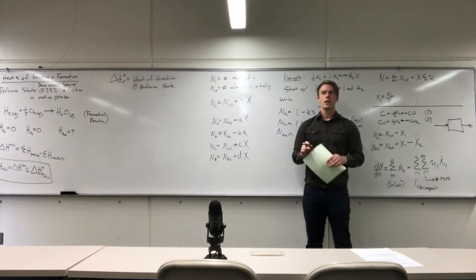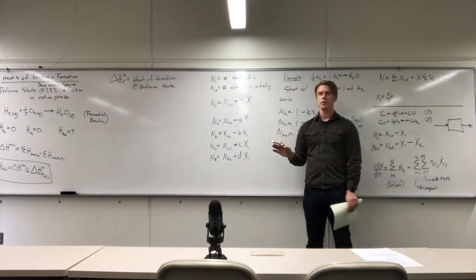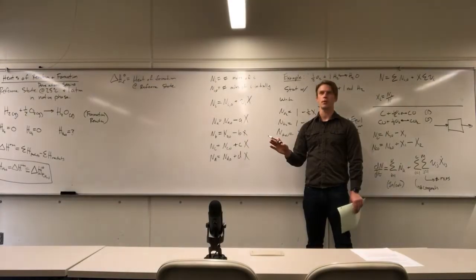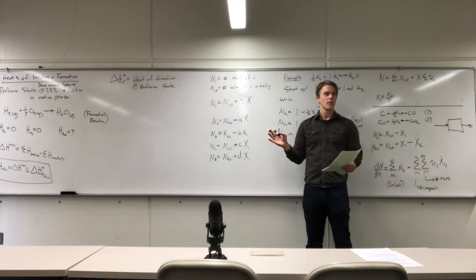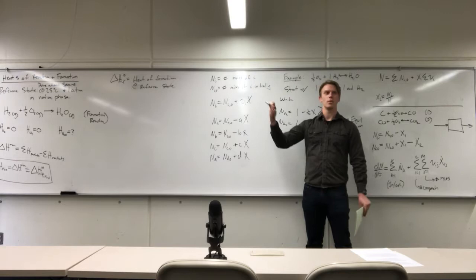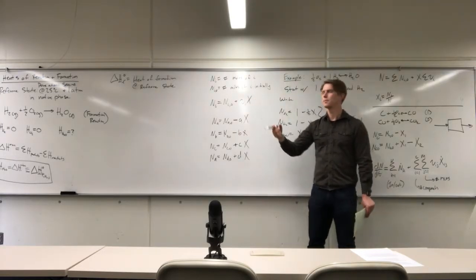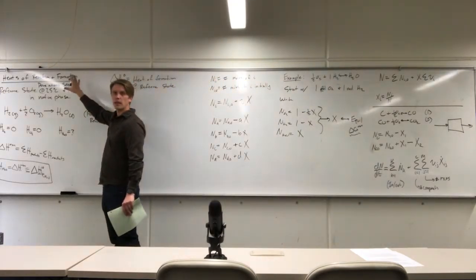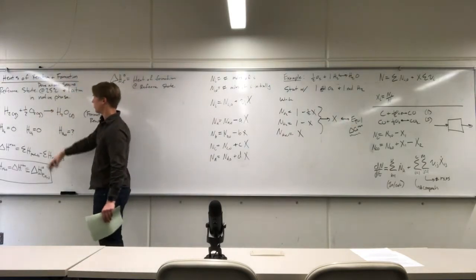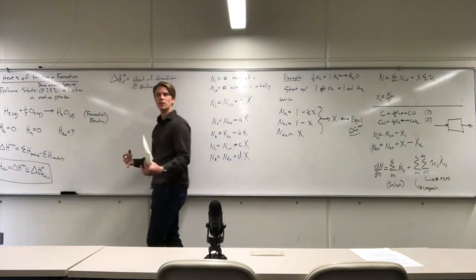Now, I don't know how many of you have used a process flow simulator or a thermodynamic software. Who's used something like that? Like Aspen Tech, Promax, anything like that. Have you ever gone and looked at the enthalpy tables? They're all these just really silly negative numbers, and it seems like it's totally made up. That's because the software program probably has some global reference state that makes it so it can be used with reacting systems and non-reacting systems. So in non-reacting systems, we can kind of choose what the reference state is to make it convenient. Sometimes it's nice when we're doing a balance to make it arbitrarily one of the inlet or outlet conditions.